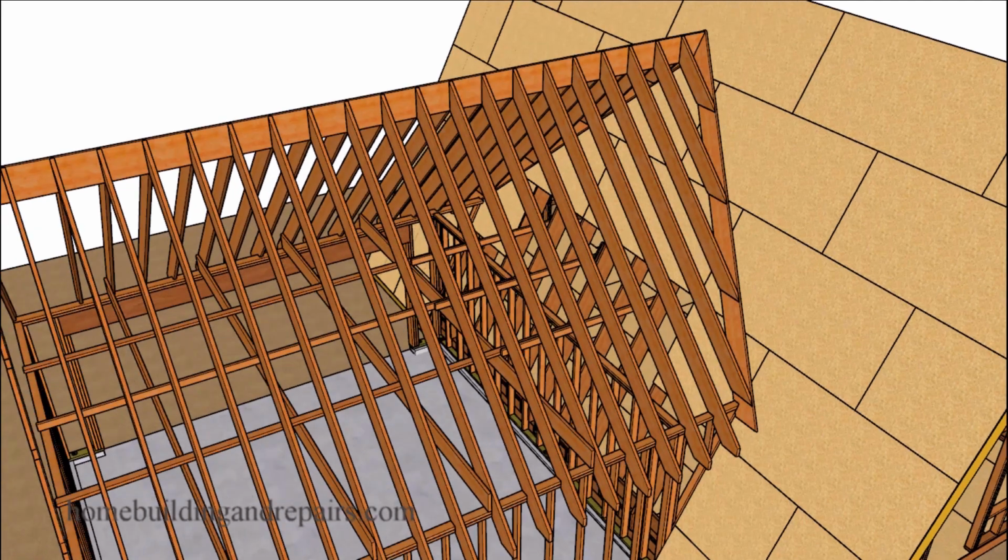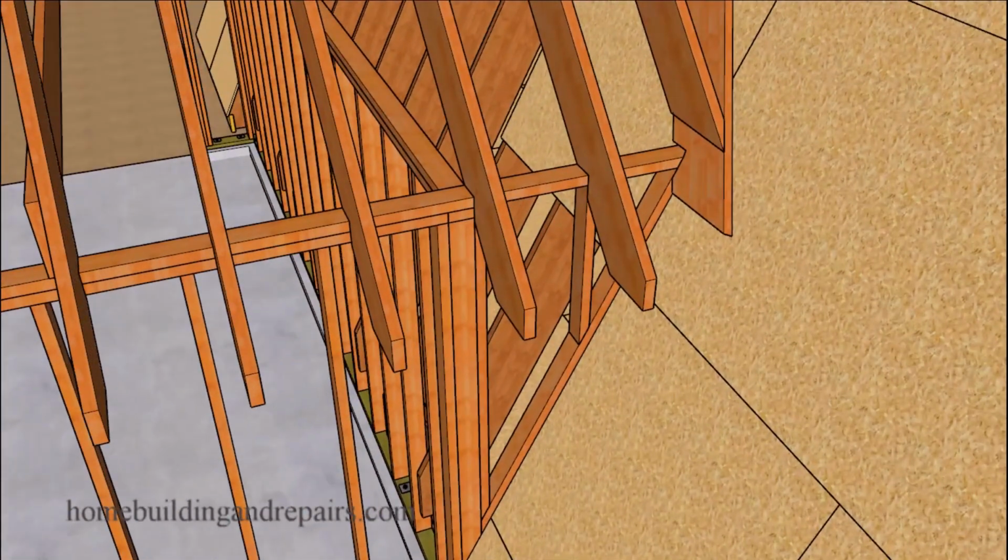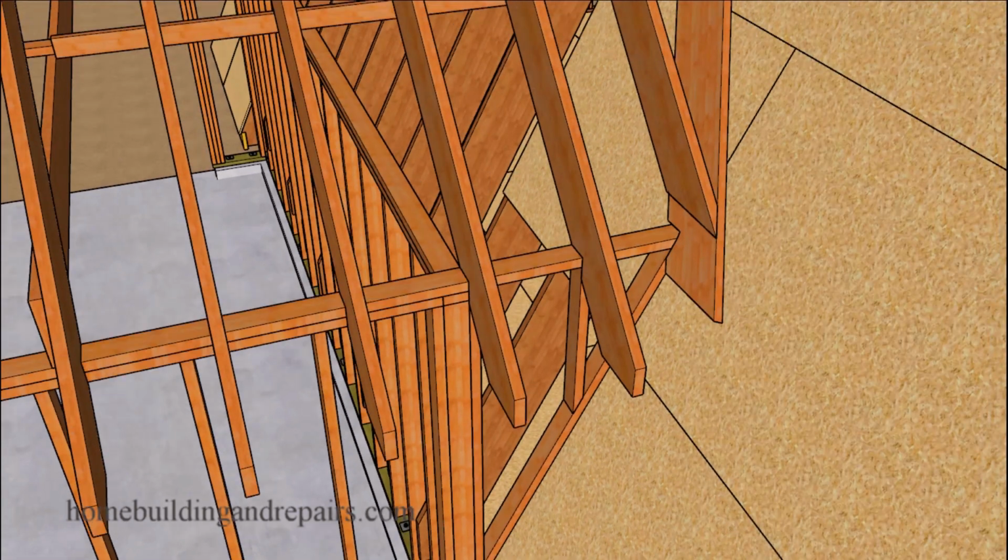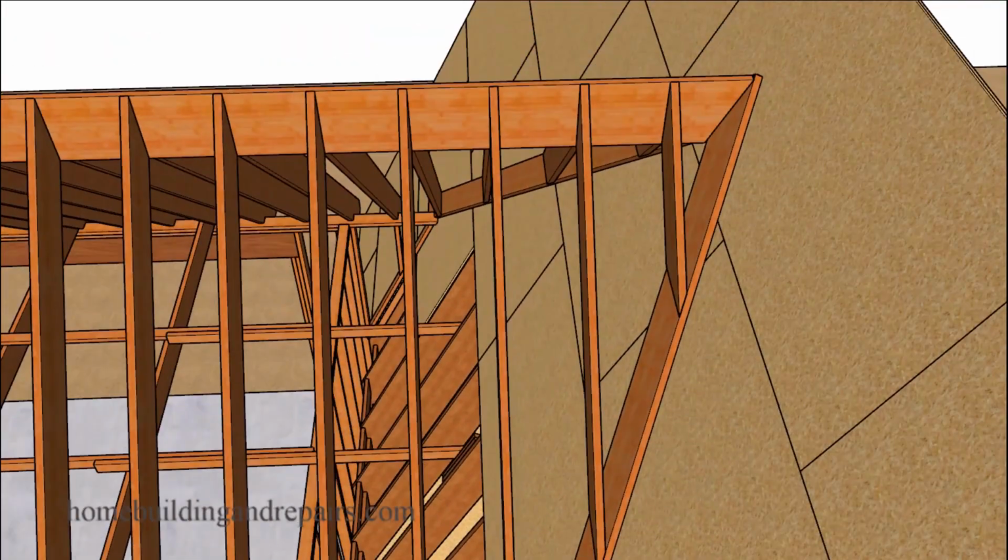Let's go ahead and put our fill in. Zoom into the bottom here to give you an idea how the rafters are going to be sitting on top of this wall here. And I went ahead and put my stud underneath the rafter since I'm going to have a single plate here. If you want to add another plate, then this wall stud doesn't need to be directly underneath the rafter. Next up, let's go ahead and take a look at the ridge.